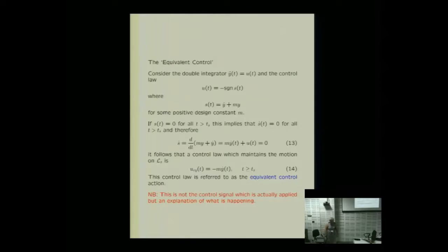Now, it's incredibly important to notice that equation 14 is not the same as the applied control. And this is a very important thing I see all the time. I saw a very recent piece of work by industry, where industry had used effectively the equivalent control as the applied control. The equivalent control is a theoretical construct. We should never use it directly in our controllers. I would advocate never using it directly in our controllers. It is a theoretical construct.